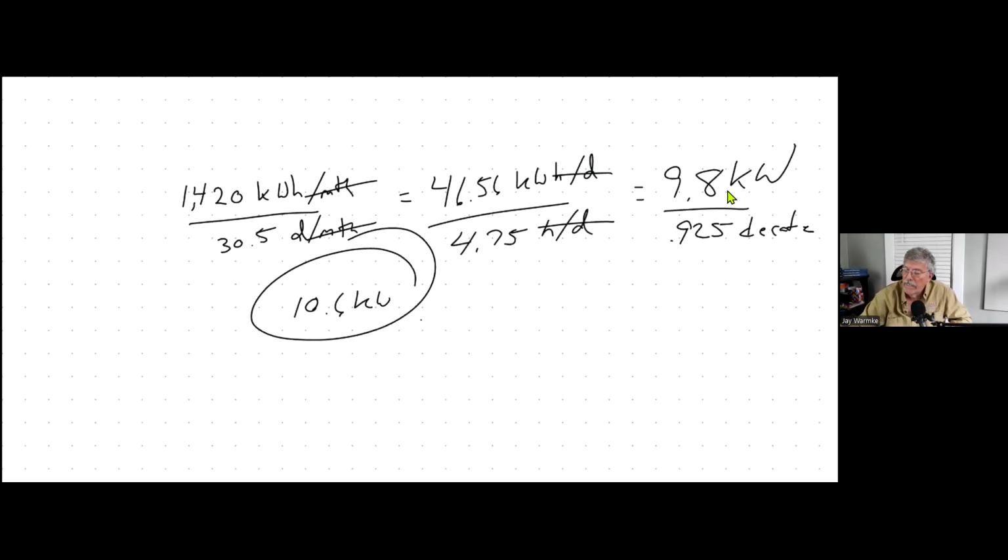You basically take the daily load, which is right here, divide it by the hours of sunlight at that location, given that orientation. You get the size of the array if it were 100% efficient, then derate it for inefficiencies. That's going to be different depending on each site. Eventually, you'll get a feel for that and you'll just plug in a number. Maybe you plug in 92.5% efficiency. Maybe it's 90% efficiency. Who knows? And then you get your number, 10.6 kW. All right. Does that part make sense so far? I'll look for your feedback there.